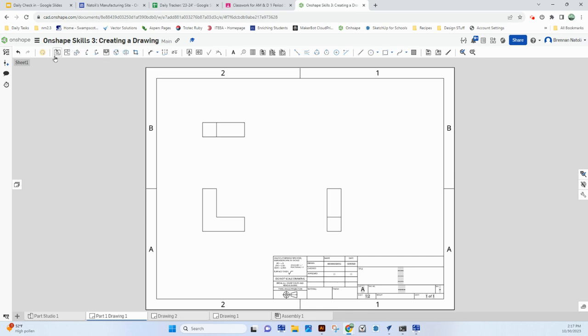If you go up into the top right, you can insert a view. There's two different ways of doing this. I can show you here, insert view, change that to isometric, and then go into the top corner and add it where I want. So that's one way. So I have my isometric, my front, my top, and my side view. I can delete by holding it, click and delete.